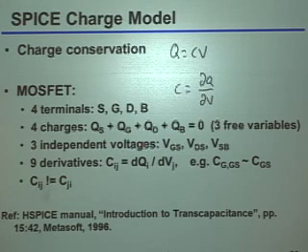Yeah, indeed, 9. You guys can at least read. That's certainly true. But it's just 3 times 3, right? Because each independent charge can be changed by each of the 3 independent voltages. Okay? So just from a notation standpoint, this is why SPICE actually gives you all of those different capacitor numbers. It actually should give you 9 different capacitors. Because it turns out that each of those is physically a distinct capacitor.